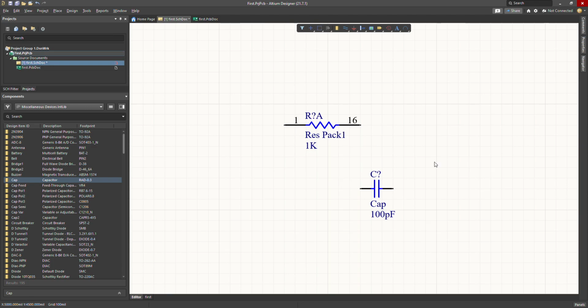To learn the macros for Altium, if you look at the list names, each of them has an underscore under the letter that activates that list. For example, if I want to go to tools, I can either press tools and then annotation and then annotate schematic quietly, which we will get to what that means. Or I can just press T and then A and then U, which are all the underscored letters for those actions. So if you want to learn the macros, that's a good way to learn them.